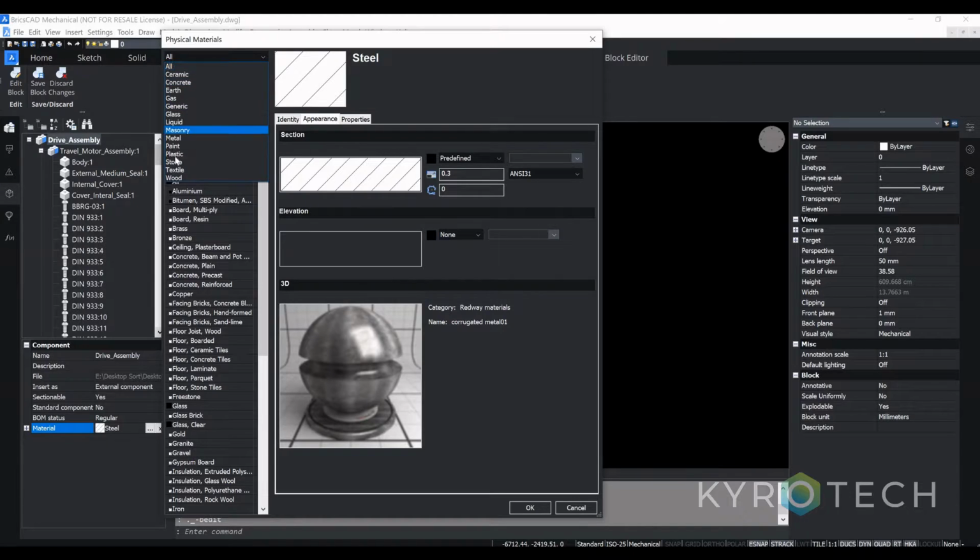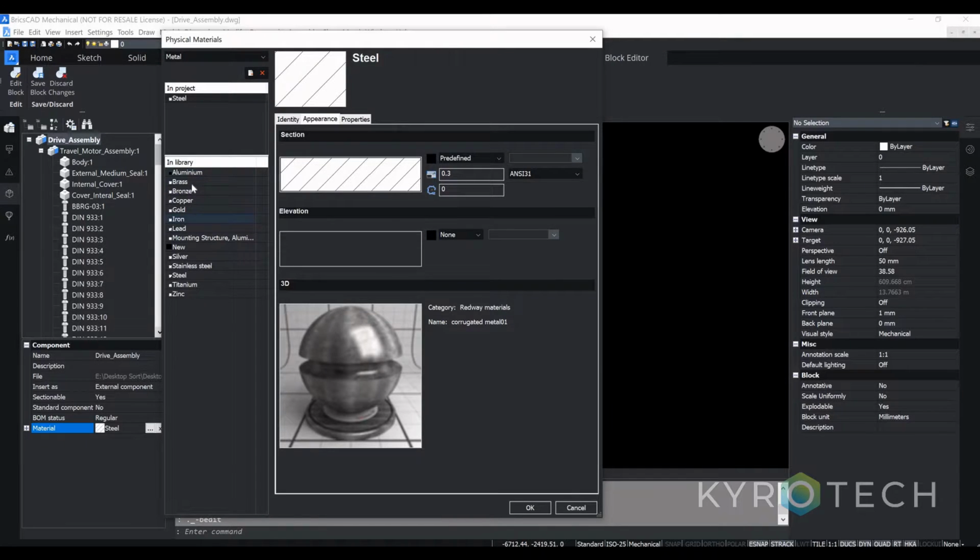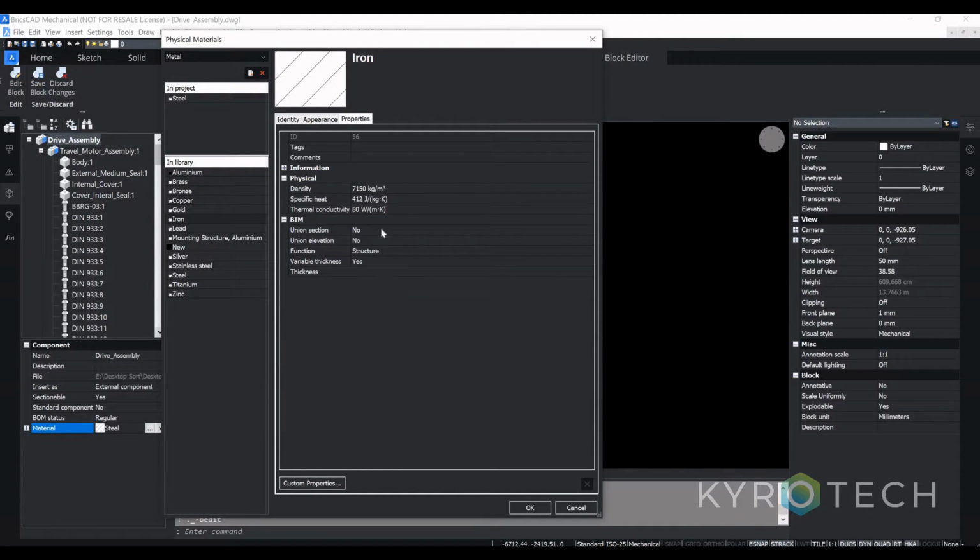If you need to allocate them depending upon what material has come to you, probably in manufacturing, these are all the different kinds of materials that you need. You can also put in different kinds of properties. This is totally editable, so you can allocate them and use them in your BOM as columns to show up, like the mass, the volume, the properties, and the material that is being used in your assembly.